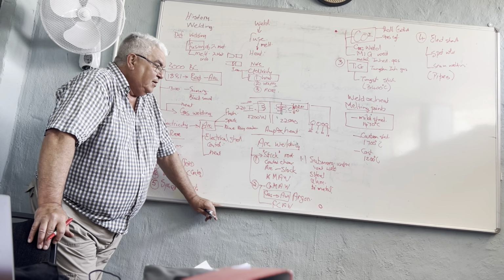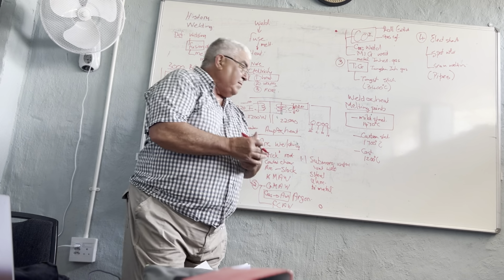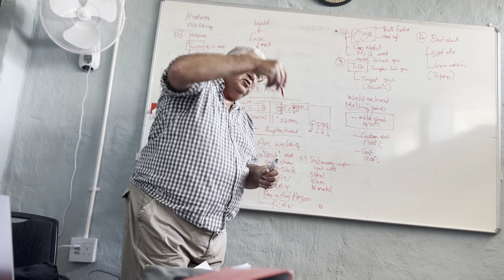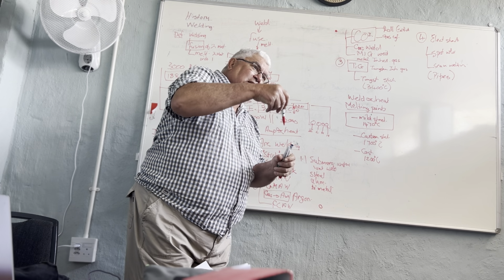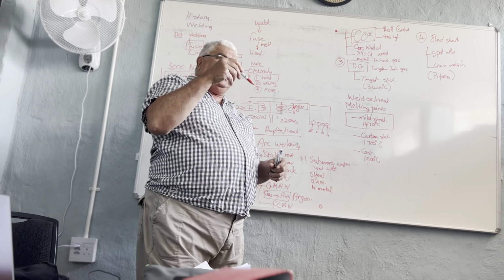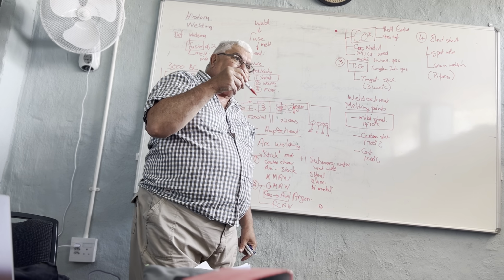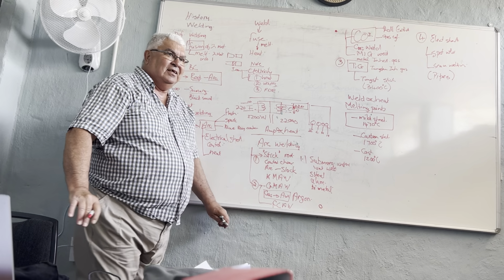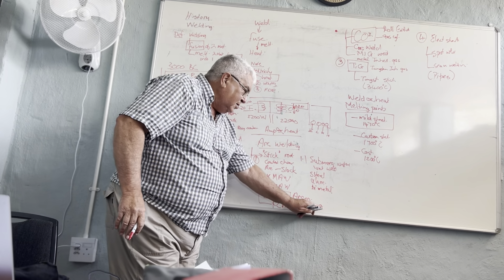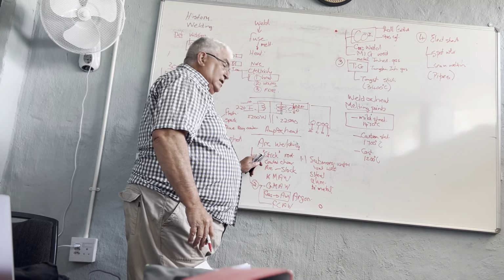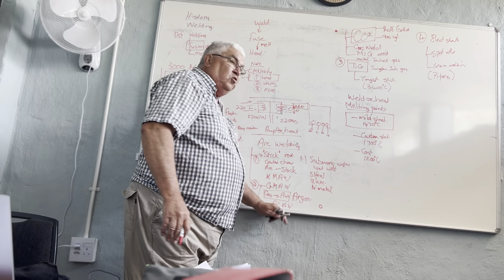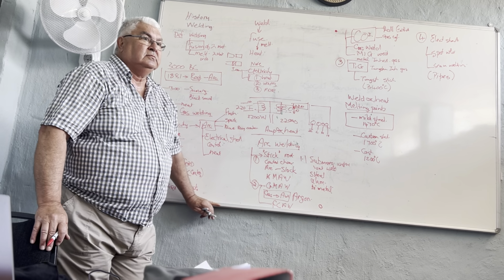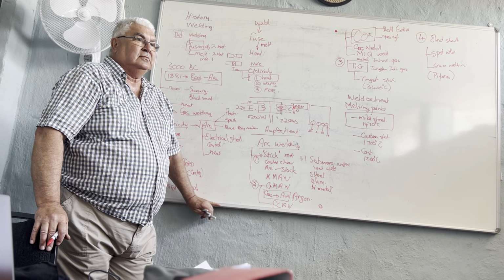Inside the wire. So that means you come in with your flux and you're coating it with steel around it. Like you're dipping ice cream into caramel, and when you take it out, the ice cream is inside. So now the flux is inside, not outside like this. It's called flux core welding. I can use it with gas or without gas.